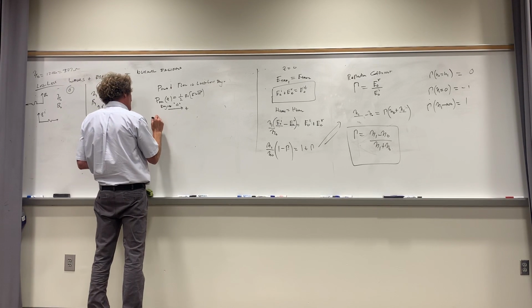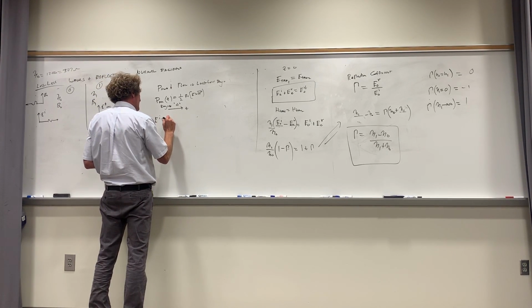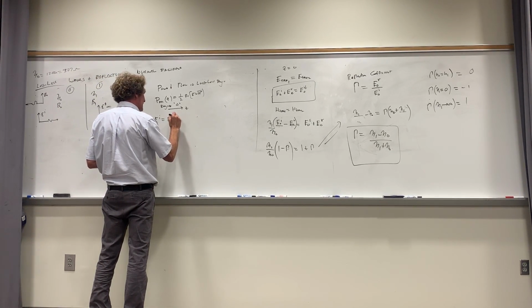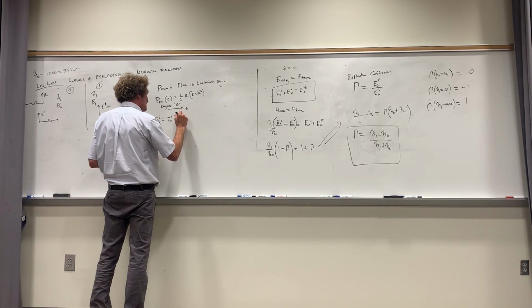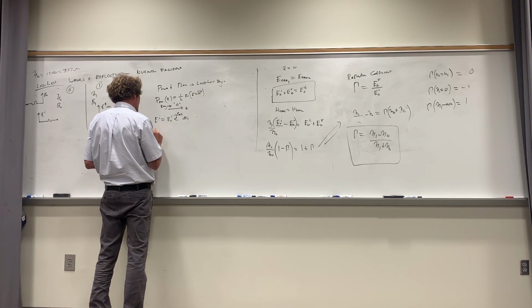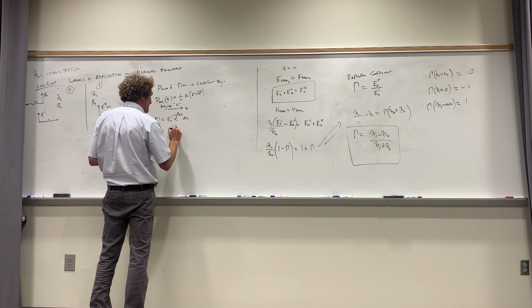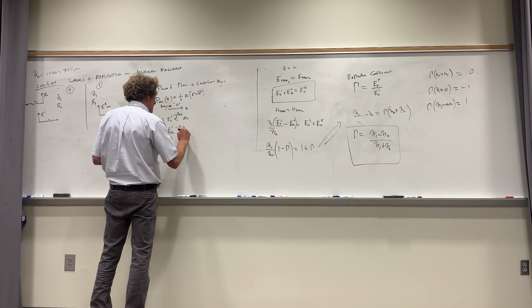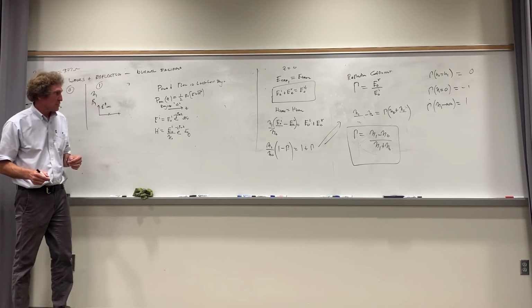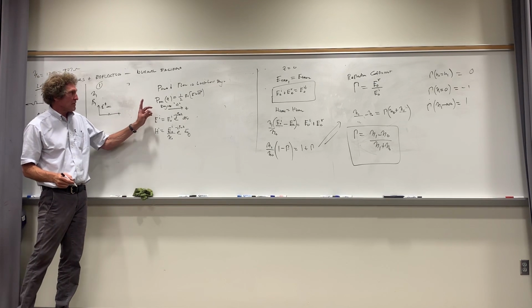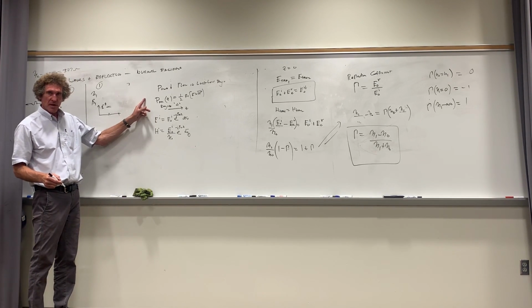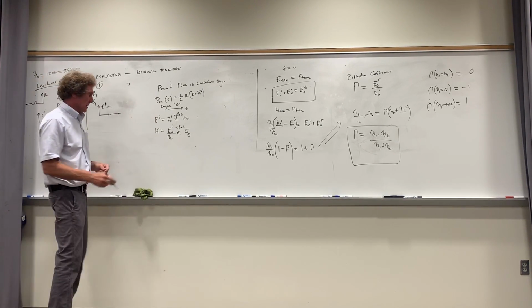So, you know the E field incident was some E naught incident times e to the minus j beta naught z ax, and the H field incident was equal to E naught incident over eta naught, it's strictly real, e to the minus j beta naught z ay, right? Now keep watching. When I evaluate this for that region, I'll do it here.